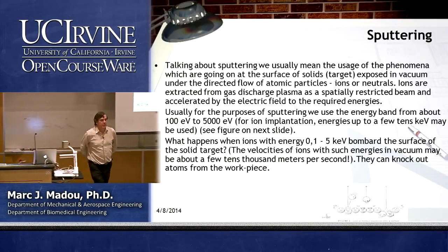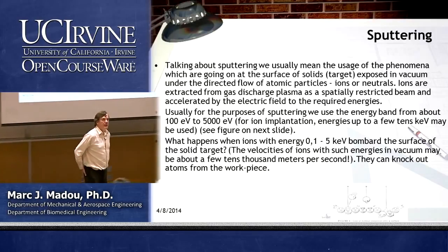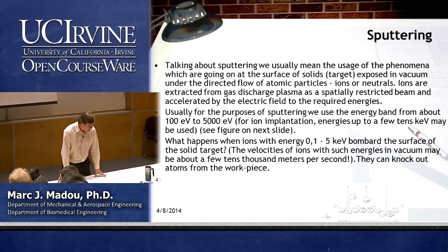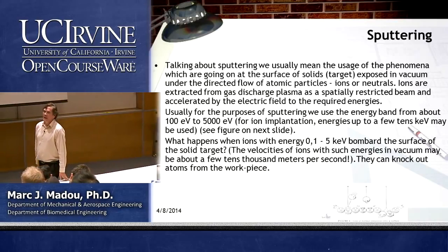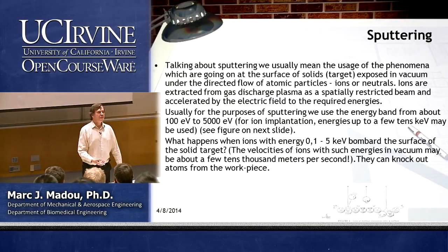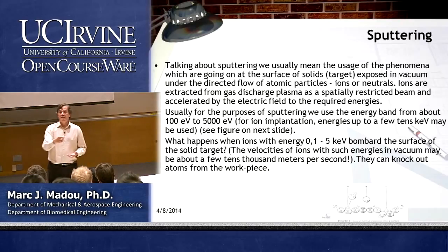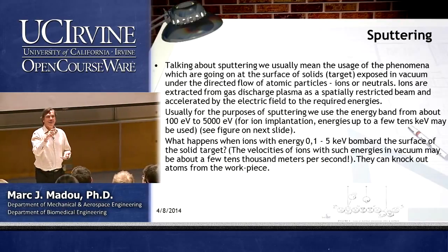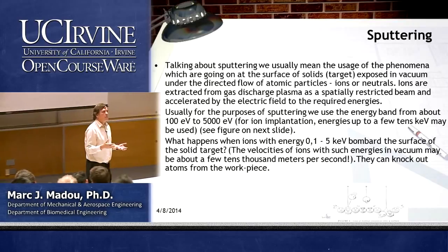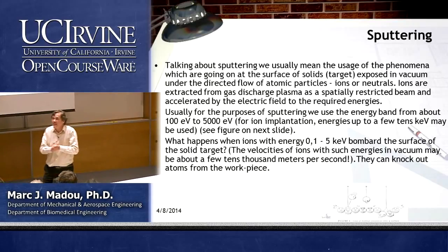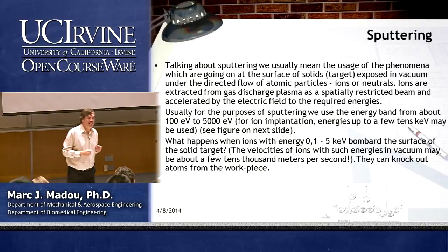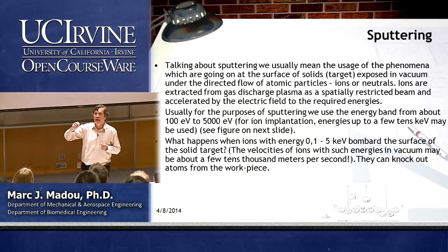So with this, I need to make a big transition to sputtering. And I have enough time to introduce you to some of the magic behind plasmas. So what is a plasma? It's another phase, yeah? Okay, but phase doesn't mean F-A-C-E, right? It's one of the phases of matter, yes? What is in a plasma? Because I'm going to need a plasma to do all of the machining we're going to do next. I need ions, so it definitely will have ions. It also has electrons and neutrals.